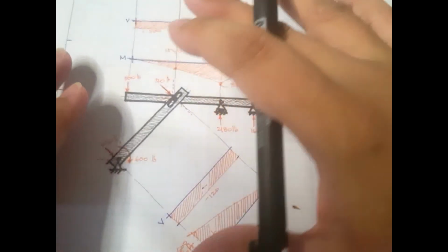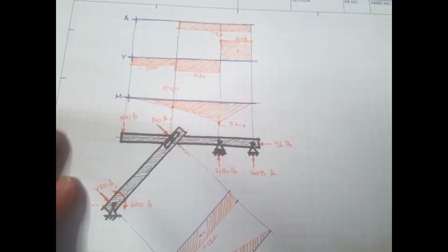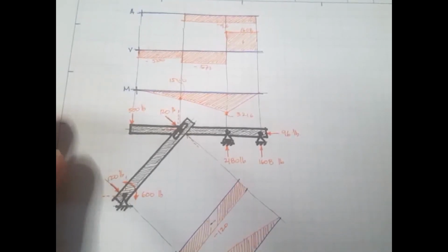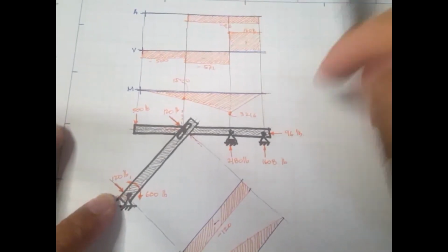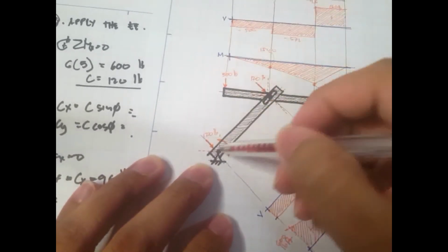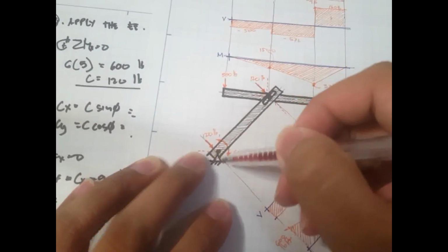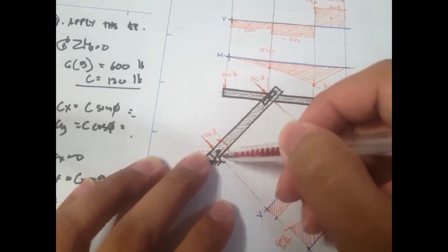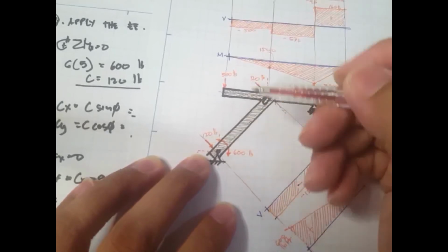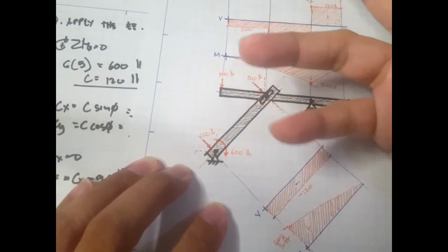Okay, so even though the problem didn't ask us to find the internal force diagram, right here we'll be doing this because this will be the basis of the stress computations. Okay, so recall that in this point A we have the cx and cy. I mean, this is ax and ay, right? But you can actually translate that, or you can take the resultant, and what you will get is actually 120 pounds, which is perpendicular to this longitudinal axis. Okay, so you can do that computation.